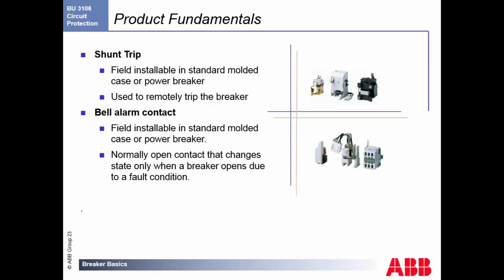A bell alarm, again, field installable. Basically, it just lets you know the state of the breaker so that if you're in a remote area, you can hear that the breaker opened and know that the power has been cut down to whatever branch, main, or feeder that you have down the line. Again, we're trying to remove the aspect of anybody going towards the breaker without having the proper PPE, which requires a half an hour, sending a guy out there.